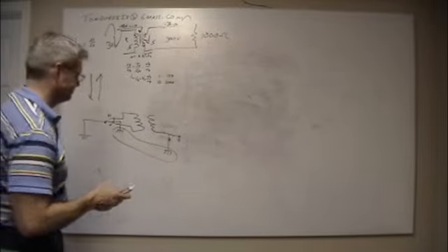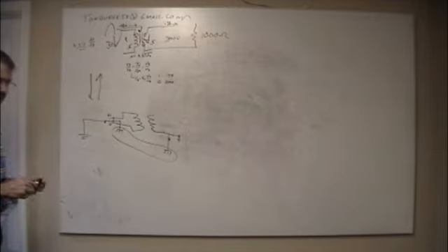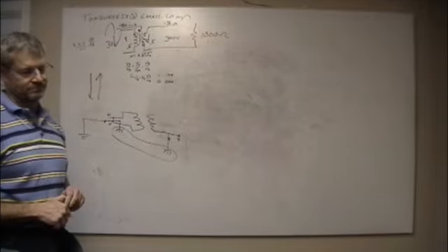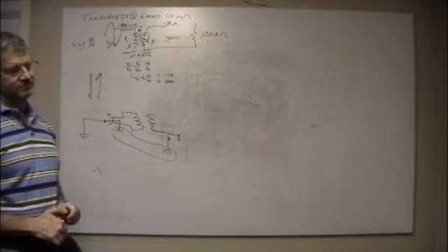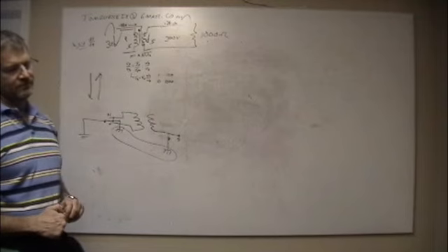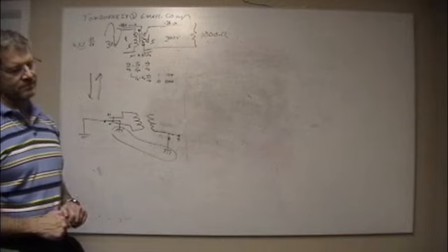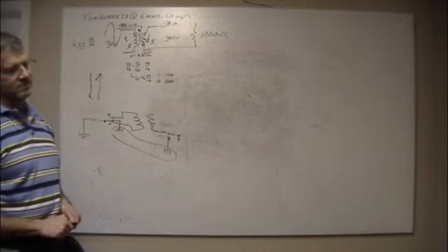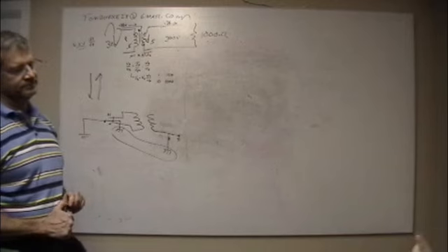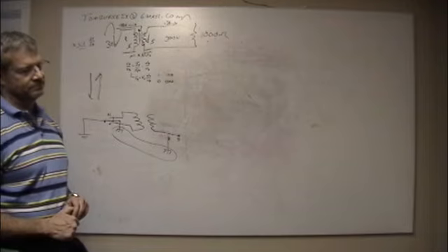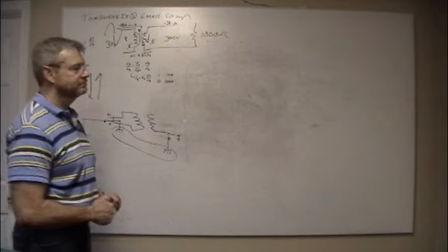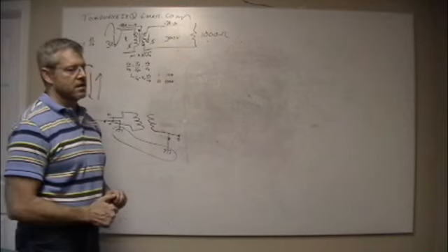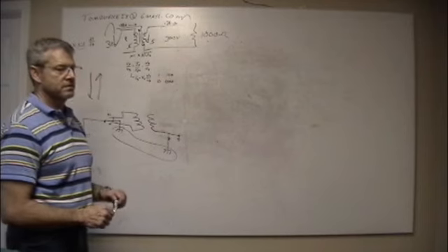And if you lose one of a 3-phase, I think it's on a 3-phase. No, it might happen on a 2-phase. If you lose one of the legs, a lot of things will work until you turn on a motor, and then strange shit happens. Light bulbs come on that aren't turned on. I had that happen in my house. Yeah, a buddy of mine had it happen.